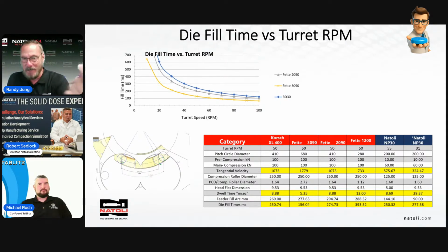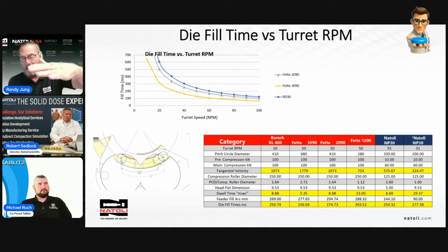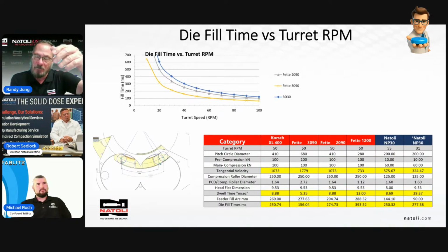The paddles are spinning over it. The powder's coming up. The paddles are spinning over it. And now I'm pushing that against those moving paddles, and those paddles are moving it to the side of the feeder immediately. So if I have all that push out, now again, I start densifying the material. And so then you say, okay, now we're going to go to a 10 millimeter fill cam. And now I'm going to push out less, and we're going to go to 8. Okay, now I'm pushing out 4 and I'm keeping 4.